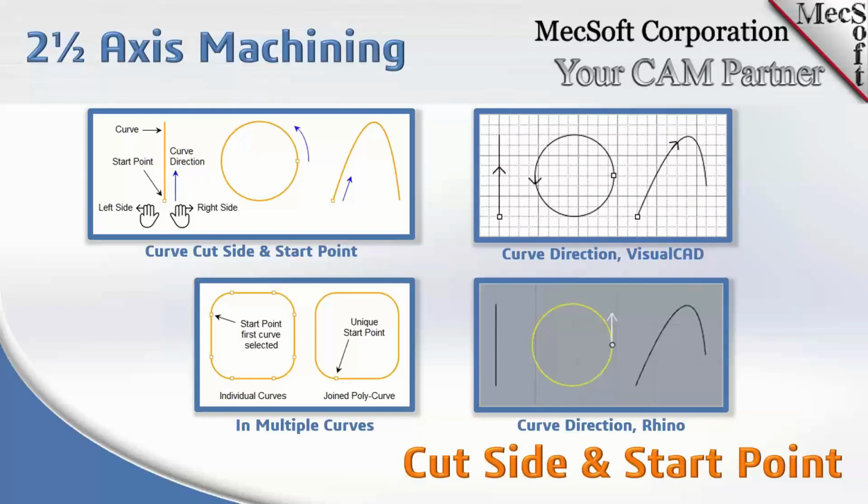If you draw a line from point A to point B, point A will be the start point as defined by the CAD system. So if you machine on that line, the start point is where the tool is going to start cutting. If you're standing at the start point and looking down the curve, right side is your right side and left is your left side.